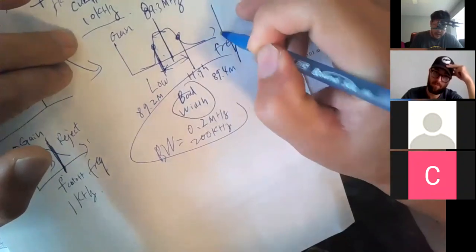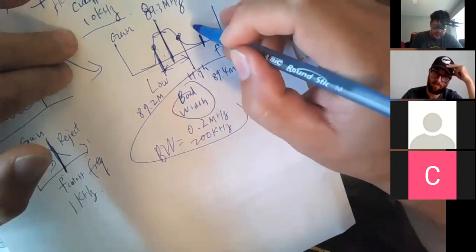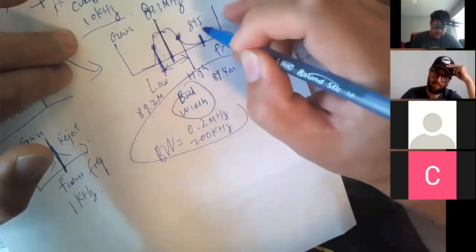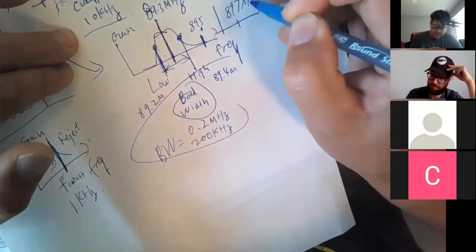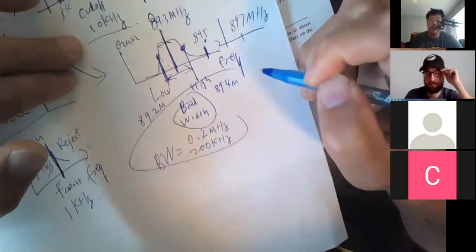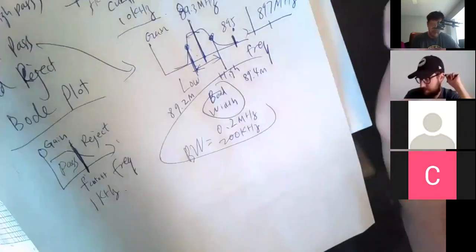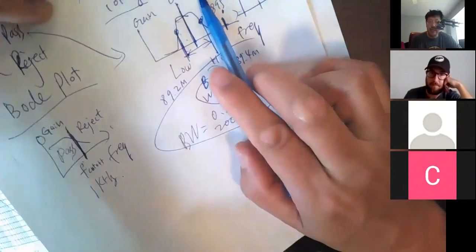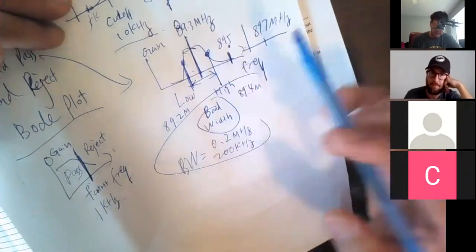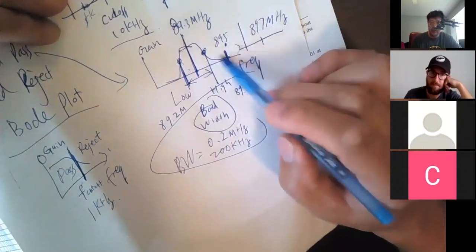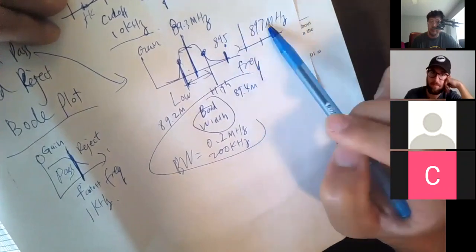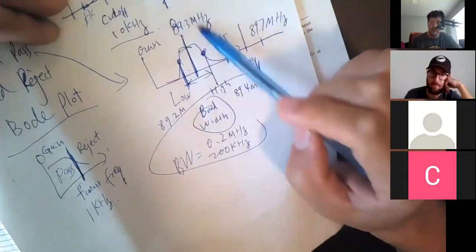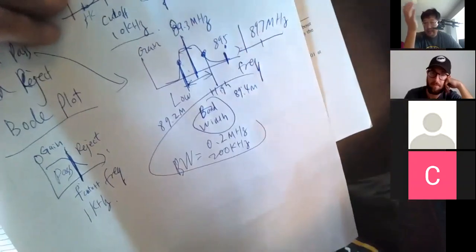So that's one station. The second station is called 89.5. The third station will be 89.7 megahertz. So those are the station carrier frequencies. When you listen to this station, you need a bandpass filter, because you don't want noise from adjacent channels, adjacent stations. You don't want to hear this, you don't want to hear this. You only want to hear the voice from that particular station.